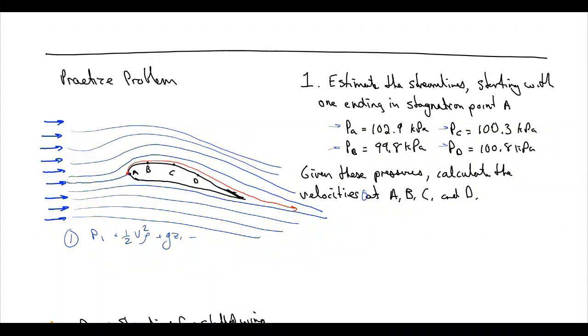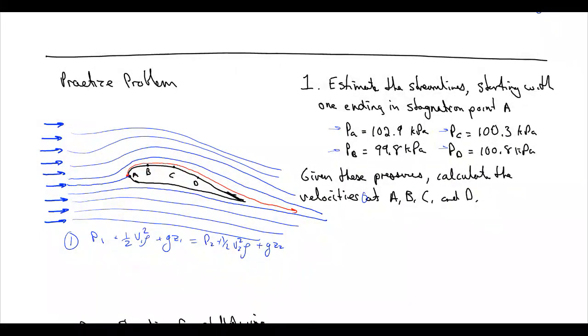We're going to have to write down some assumptions now, again, to help ourselves, our future selves, our future coworkers, and the graders. We're going to neglect height because it's a gas. We're going to assume inviscid, and we're going to assume rho is equal to a constant and steady state.